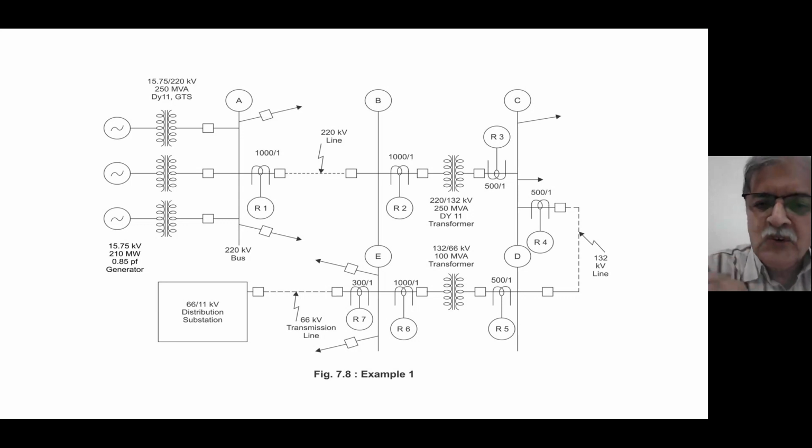While calculating 0.25, I have considered three things. One thing, relay errors. I say that relay R7 will operate within certain time as per formula, but all relays, 100 relays that is manufactured by manufacturer may not operate exactly at that time. There will be some time margin, some time error. You have to allow for certain time discrimination errors, time margins.